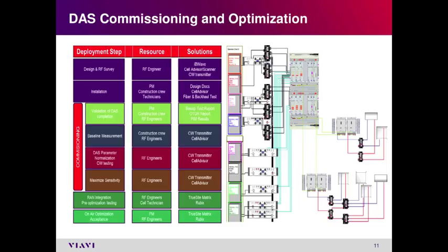Once you do all of that, then you go into the RAN integration, where you hook up your RF link if that DAS requires an RF link to be connected to the conditioning equipment. In some cases, you will see certain DAS where a digital signal from the baseband unit can be directly connected to the head end and converted directly into fiber. So you will not need the conditioning equipment or the attenuators in the middle.